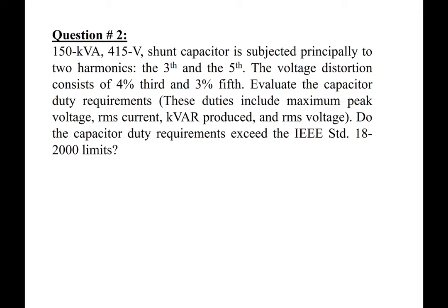Let us now look at question number 2. It says that we have a 180 kilovolt ampere shunt capacitor, and this is subjected to third and fifth harmonics. The distortion consists of 4% for the third harmonic and 3% for the fifth harmonic. Evaluate the capacitor duty requirement.